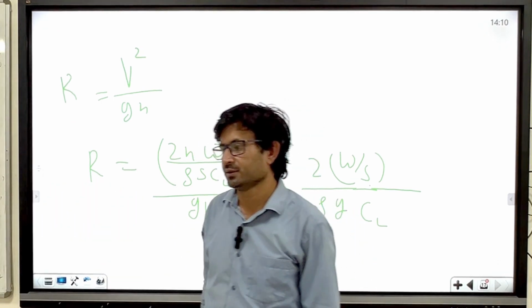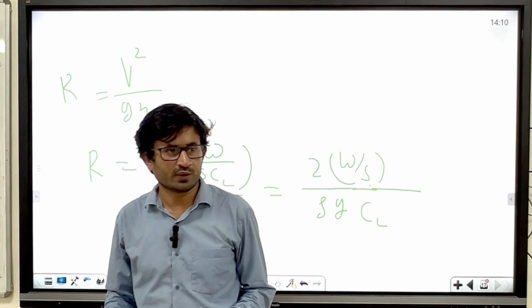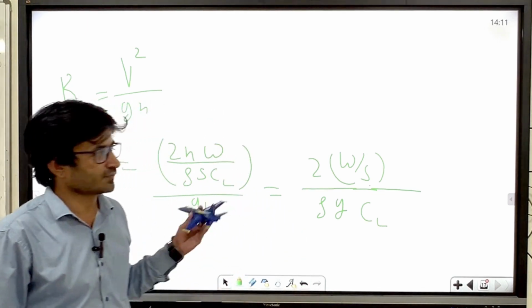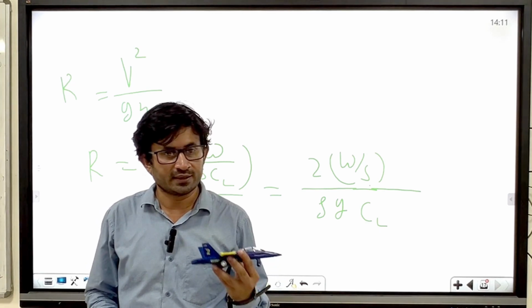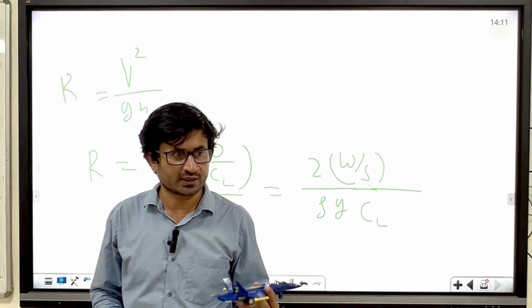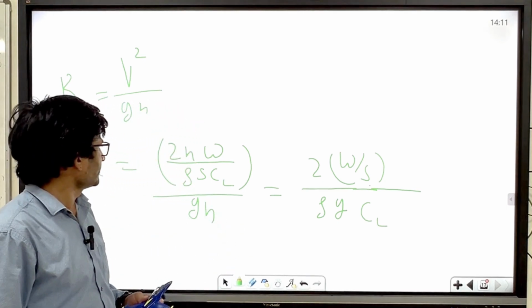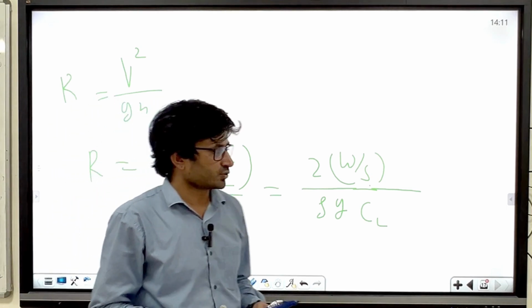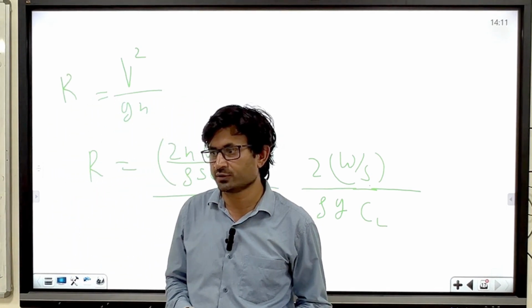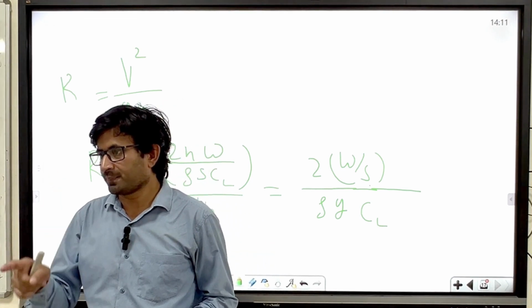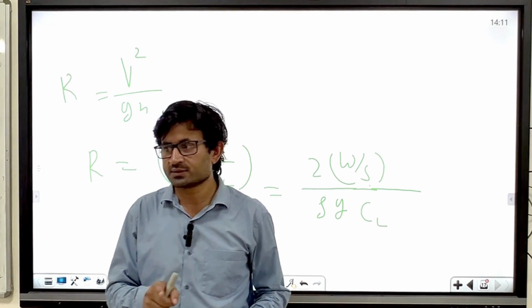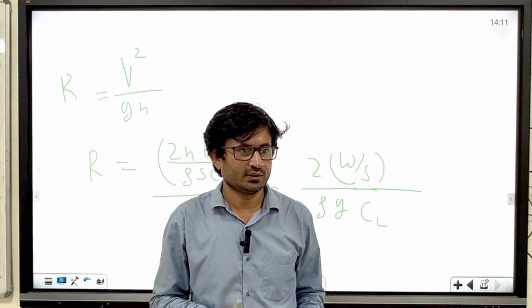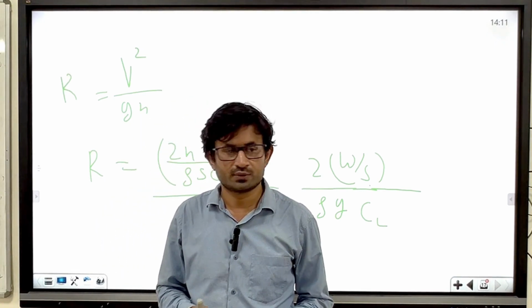So we have seen in this lecture what is pull up and what is pull down and a generic case, and we have derived the expression for the turn radius as well as the turn rate for each considered case. And we have found the omega max and R minimum condition also. And we have also seen that if you fly with a very high load factor, in all cases, your level turn, pull up case, pull down case, your radius of turn will be equal, and your turn rate also will be equal. So thank you very much.